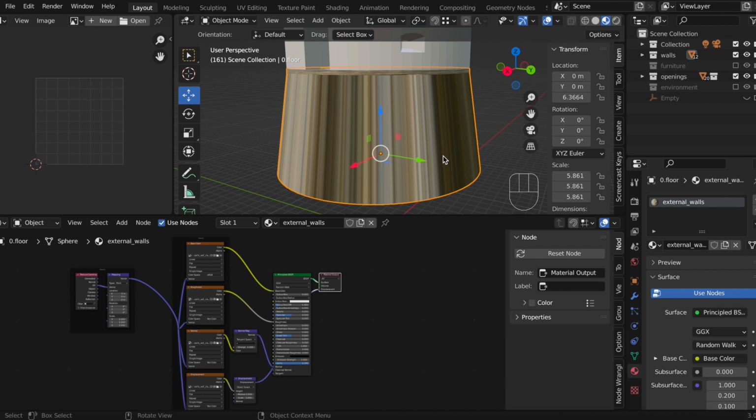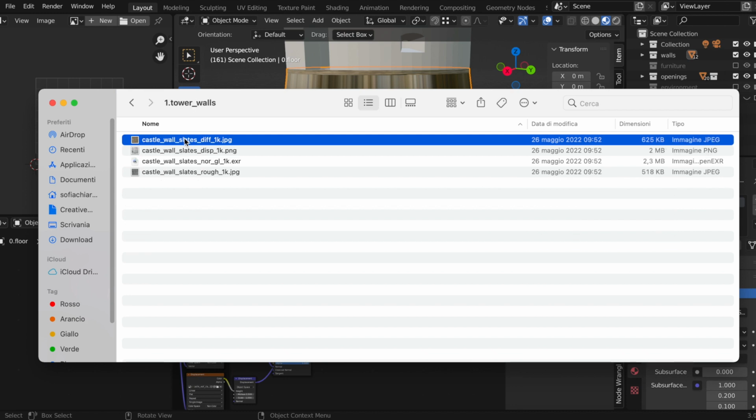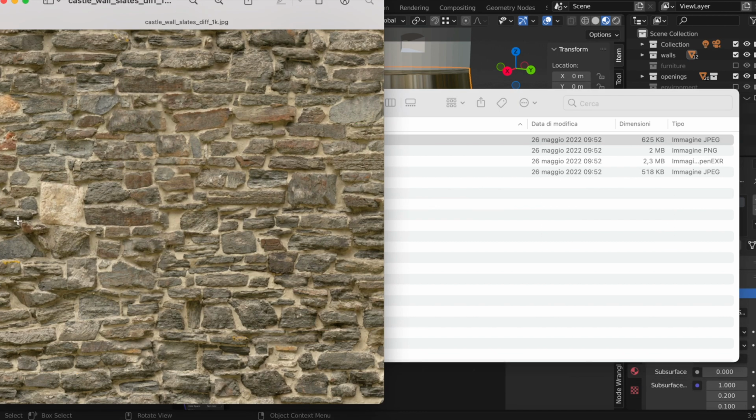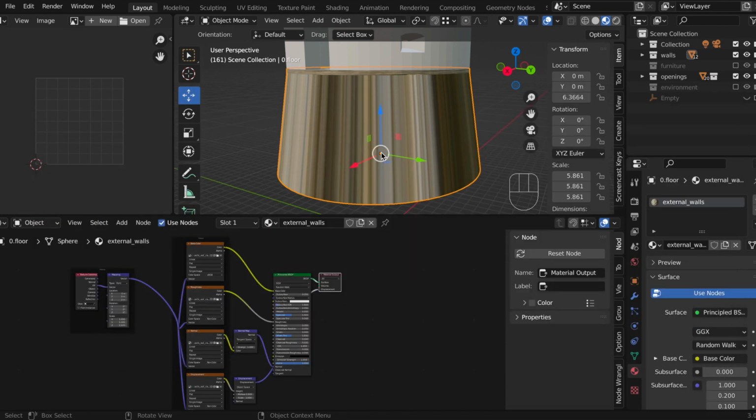As we can see, the texture is not well placed along the model, because it should be as in the image we see in our folder. So, if we have this situation, it is because this part of the model was created through an extrusion and therefore stretched the faces. It is up to us then to properly set the texture adhesion to the model.